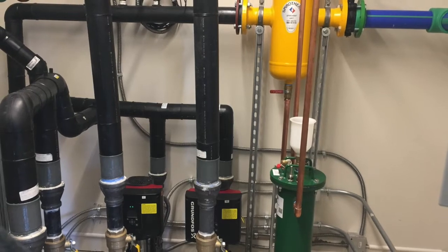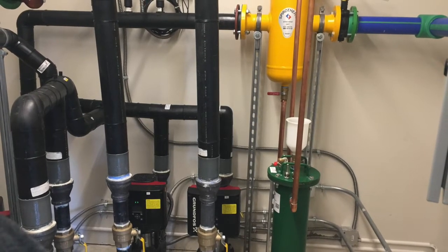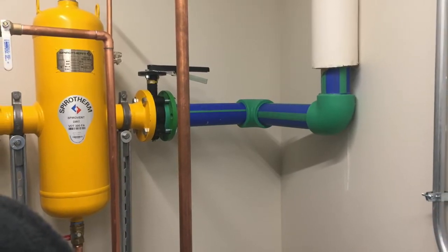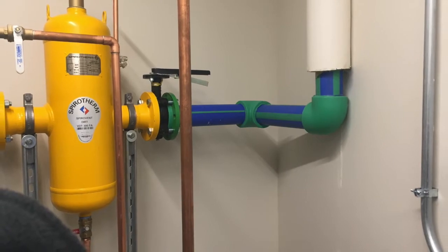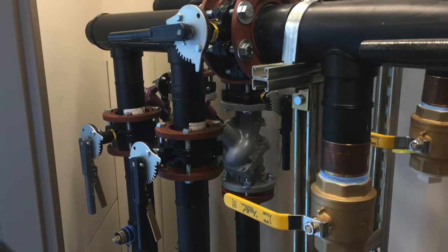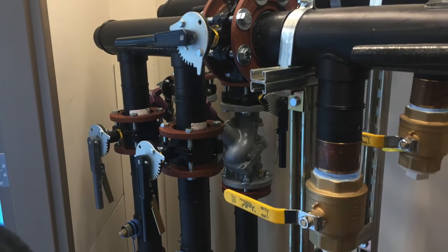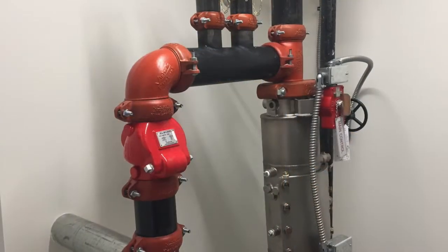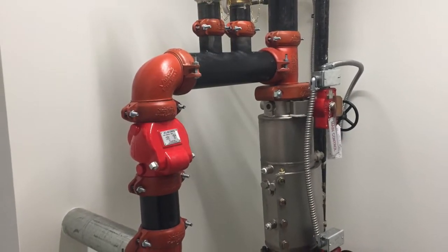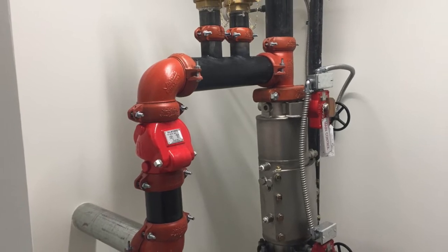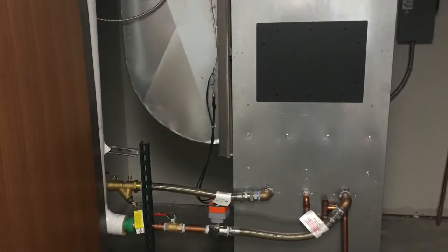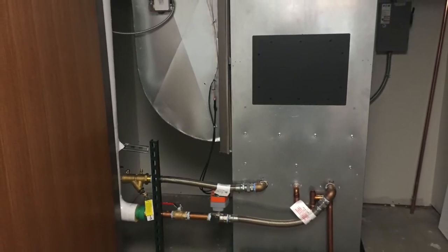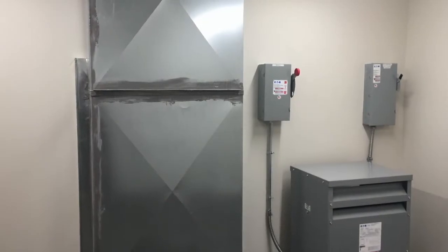As we advanced in heating and cooling technology, we learned that buildings could be heated and cooled using a ground source heat pump. These systems were called geo-exchange systems, which exchanged temperature from the earth to the building and the building to the earth. In the winter, the cool temperatures in the building are exchanged with the warmer temperature in the earth, and that is reversed in the summer months. In Lafayette, Colorado, the ground temperature at a depth of 8 feet in the earth generally stays around 58 degrees Fahrenheit. Currently, these systems are referred to as ground source heat pump systems.